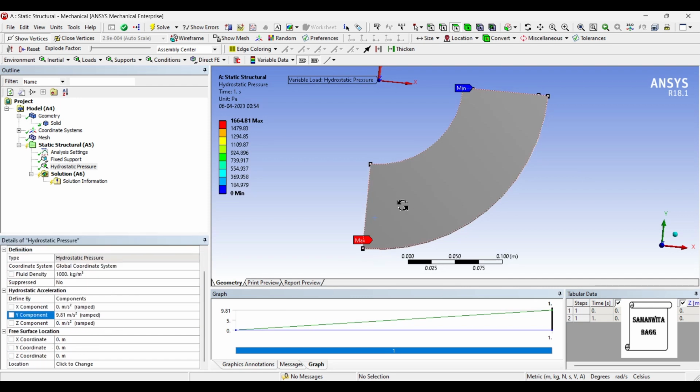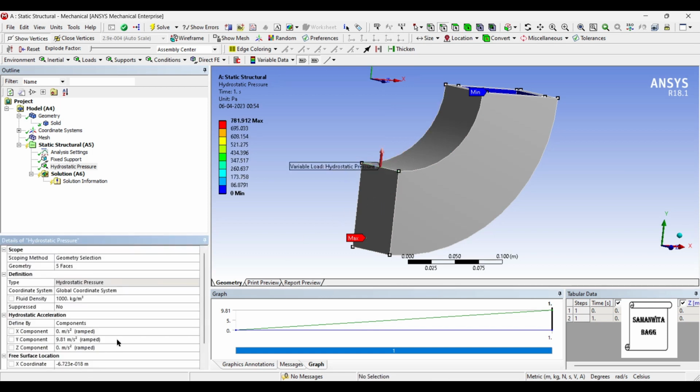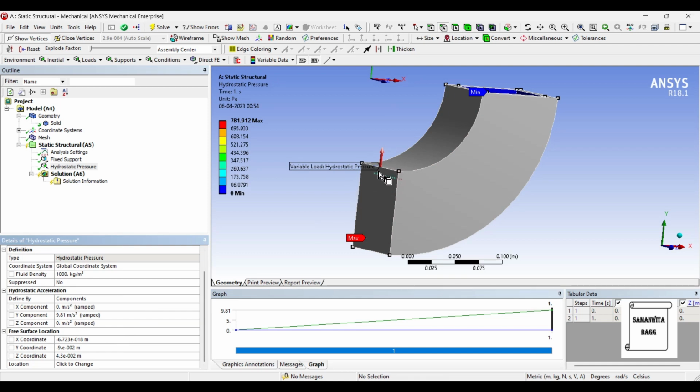Now for the x, y and z coordinate, I will click on this option of location and I will choose this h and apply, because that's the value that I know. So I want to calculate at a depth of some value. So I will just change this y coordinate and I will try to get the answer. So that is 9 centimeter, if you know. So I'll just change this units to centimeter again. This is 9 centimeter. The difference between 9 and 18 is 9.